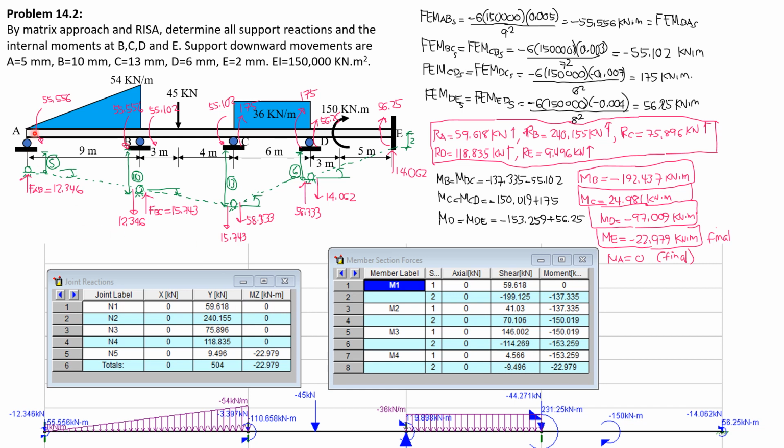By the way, when the beam is end supported, the technique here is that the final moments at A and at E, as long as they are the leftmost and the rightmost supports, would be final also, except for moments at B, C, and D which are not final. And remember also that the vertical reactions will also be final after we apply these side sway moments together with the loads.